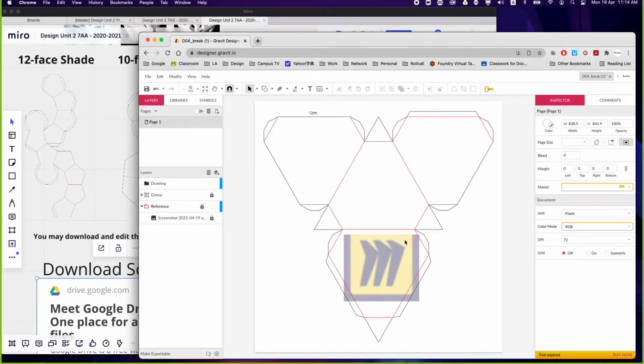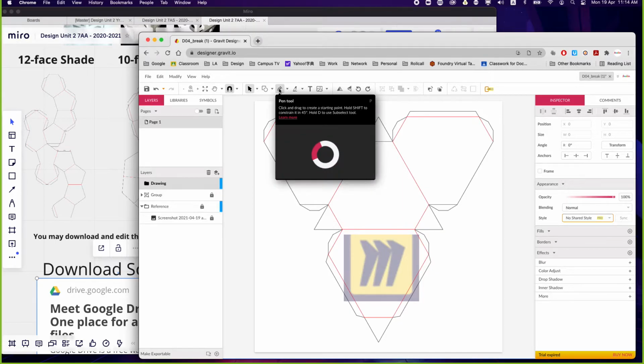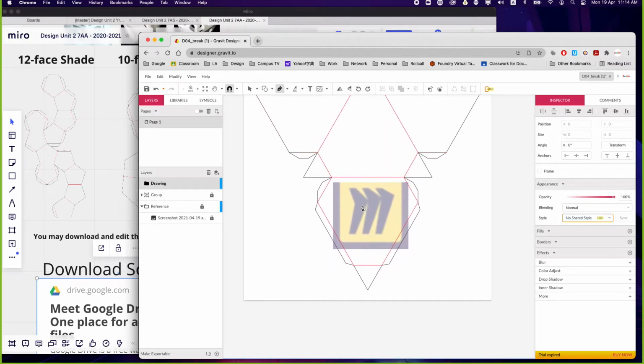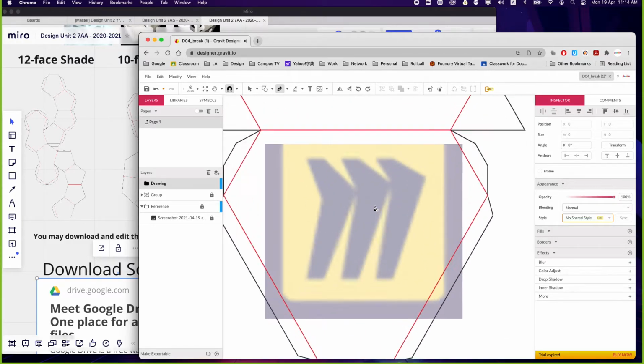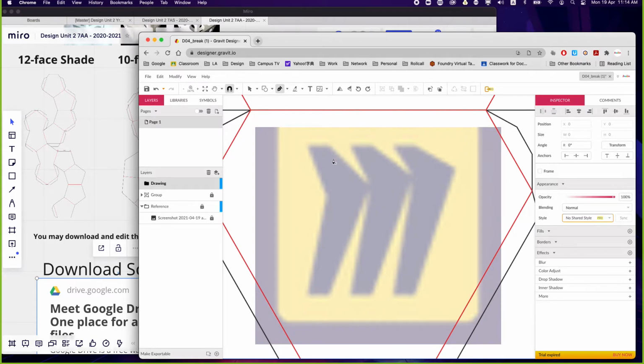So now is the time for me to draw the path, draw the Bezier line according to this reference. So I have to first select the drawing layer, and then I enable the pen tool either by clicking the P key on your keyboard or just clicking on top here and selecting the pen tool. Next, I try to center this image, pinch in a little bit so that it fills up my screen for a more accurate tracing.